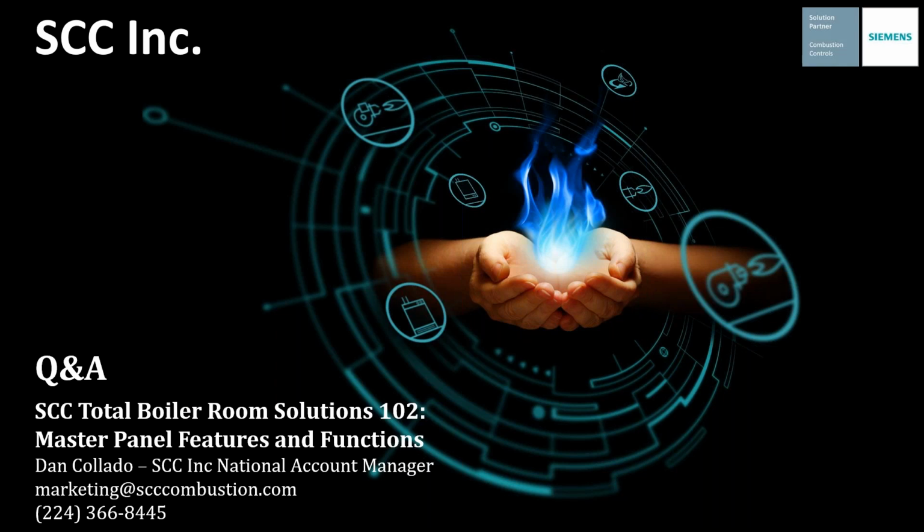Okay, again, a very common question. I'm not surprised it was asked again, but the answer to that is basically no. Big picture, the master panel, our local touchscreens and PLCs are digital communication devices, and there's a lot more programming than you realize that goes into making these products. So for applications with third-party controls that require lead lag, auto rotation, hot standby, low temperature, low fire hold, the minimum requirement that we need at each burner boiler is an RWF 55.